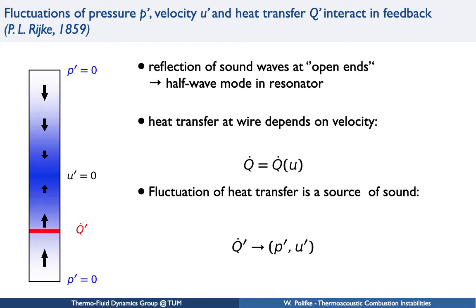And the sketch here on the left illustrates, on the one hand, the velocity vectors. At this snapshot, everything would be flowing towards the center, and as a consequence, the pressure in the center would build up. This is what is indicated by the blue color. So clearly, in a standing acoustic wave, or in any acoustic wave, pressure and velocity talk to each other. There is feedback between these two quantities.